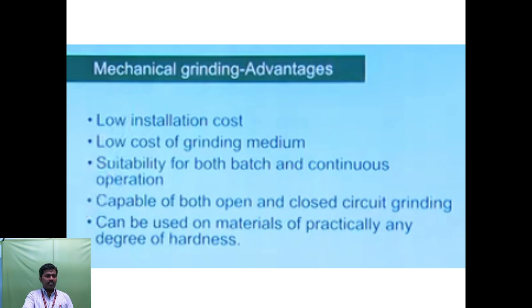The advantages of mechanical grinding are low installation cost, low cost of grinding medium, suitability for both batch and continuous operation, capability of both open and closed circuit grinding, and it can be used on material of practically any degree of hardness.